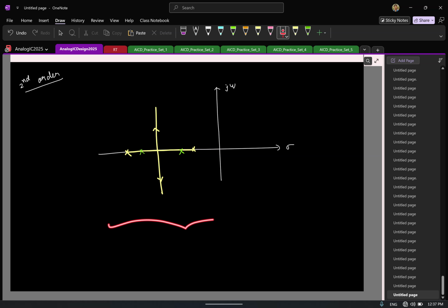This is a closed loop system. Okay, I don't need to approximate at all, right? Think of it like this is a closed loop system. I have two poles which are far apart. So let us say I call them PA and PB, pole A, pole B. Of these two, which is the dominant pole? Low frequency pole is the dominant pole. So which means the settling here will be determined by which pole? Because this is a low frequency pole, the speed will be determined by this fellow.